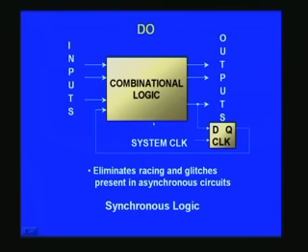And here you see that whatever combinational logic you have inside will produce this output, and this will be processed only when the system clock arrives, that is at the rising edge if it is programmed for rising edge direction. The Q output is naturally delayed by 1 clock pulse, because this will take effect for the next iteration or whatever you call next processing only at the next clock pulse.